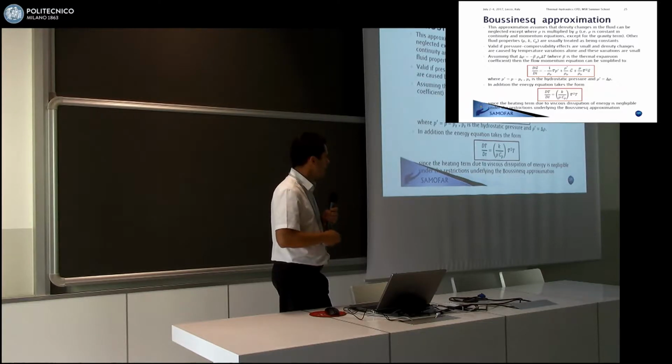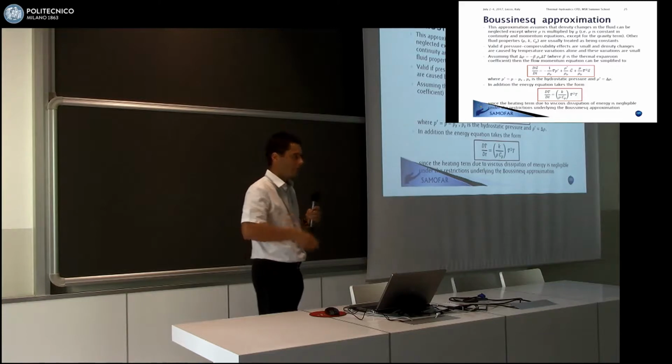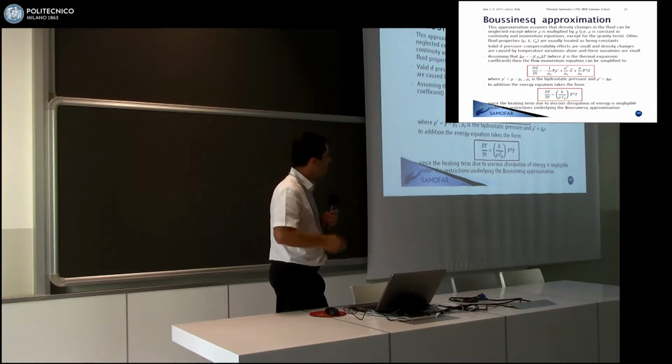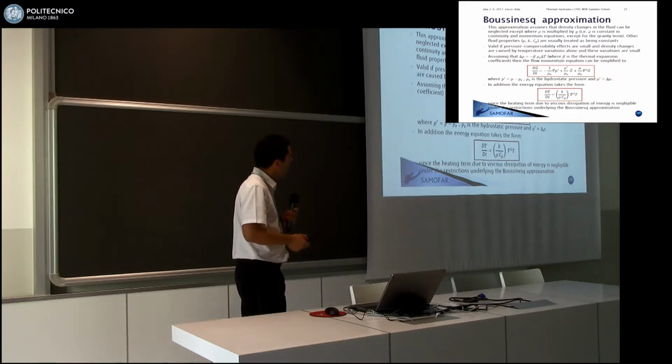These two, the inertial and the viscous forces, are the two that will decide, the difference between the two will decide whether the flow is laminar or turbulent. If the velocity of the fluid is high enough, the inertia term will become very important, the equation will be very nonlinear, and then you will have turbulence. On the contrary, if the viscous forces are very important, like close to a wall, then the solution of the equation will be a little bit easier. You have fewer instabilities, and you will have a laminar flow situation.